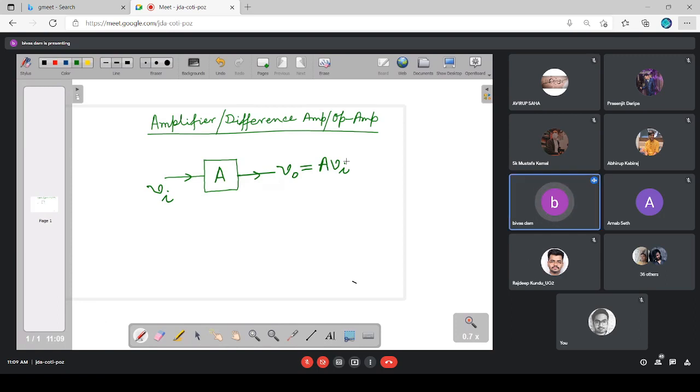So basically, what is the purpose of the input signal? The input signal is having effect on the output in such a manner that though the output voltage is coming from the DC source, that output voltage is as if getting modified, some sort of modulation, though I should not use the term modulation in the true sense. Rather I can say that the output voltage is getting the waveform nature of the input voltage, but the source of the extra energy or the extra voltage is nothing but your DC.